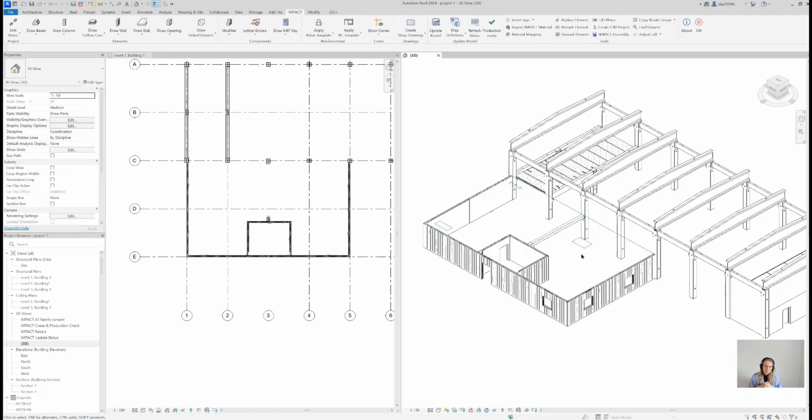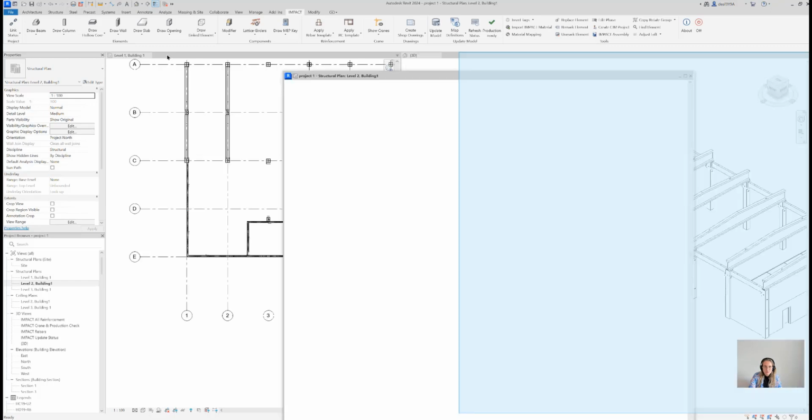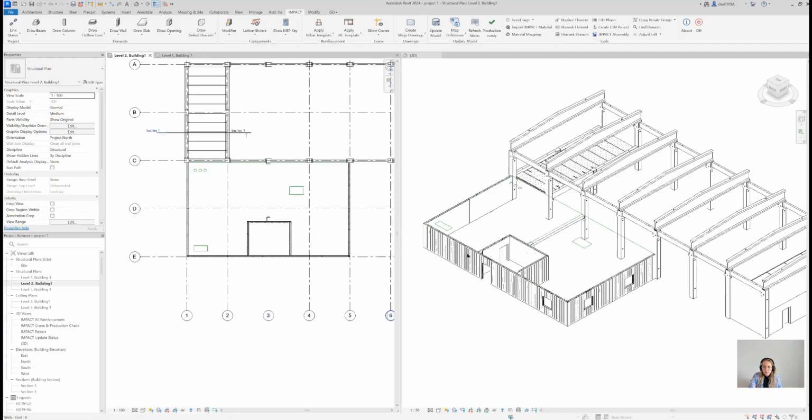I am going to draw some form slabs here on the top, and I'm going to add some holes, as we call them, recesses in form slab. So in order to draw form slabs, I think we're going to need to do it on level 2, like this. If I move it on the left side.